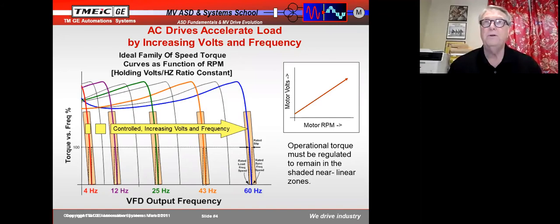What about the current into the drive? Well, the voltage into the drive is always from the line, right? It's 100%. And therefore, our current is only 10%. So out of the drive, we have 10% voltage and 100% current. Into the drive, we have 100% voltage and 10% current. It kind of acts like a transformer there.